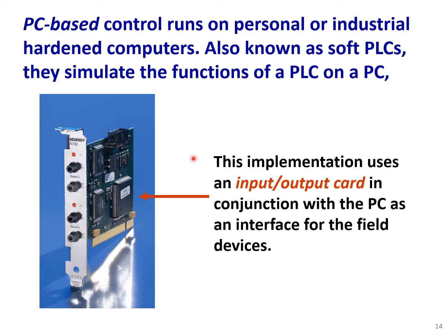The implementation uses an input-output card in conjunction with the PC as an interface for the field devices. So it simulates our PLC, but of course we cannot use these types of PCs and input-outputs in an industrial environment because of the less durability and less reliability of this type of PC.